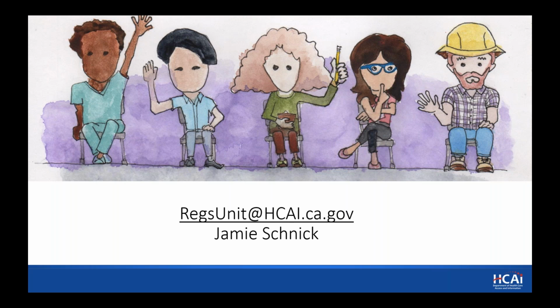Thank you. Let's continue. Question reads 517.19, category 1, critical care spaces. A, patient bed location branch circuit. Each patient bed location should be supplied by at least 2 branch circuits, one or more from the critical branch and one or more circuits from the normal system.